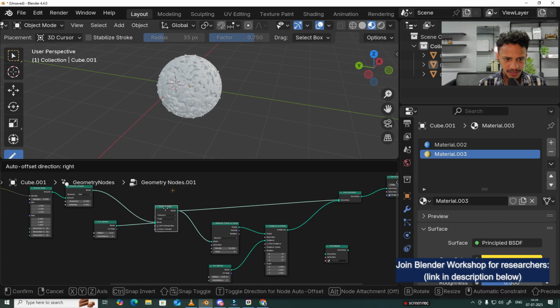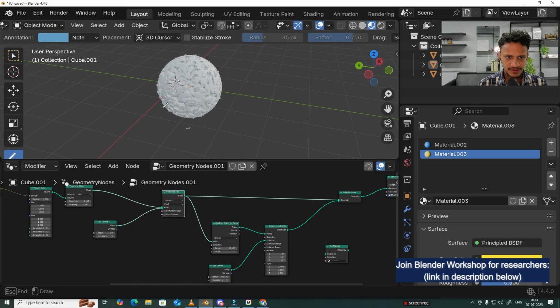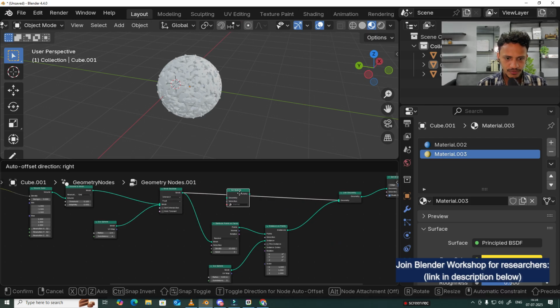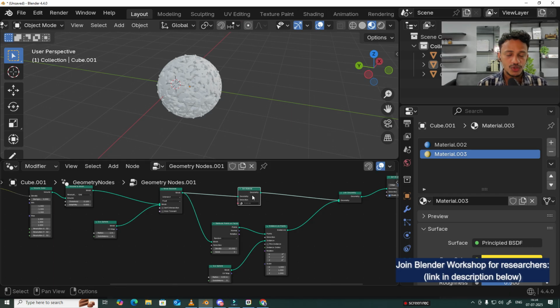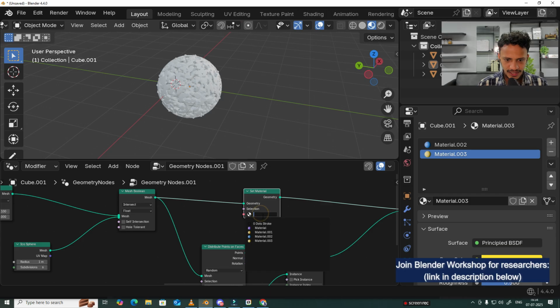First, the mesh boolean output, which gives you the particle itself, and then you have all these tiny spheres. So we need two materials. So add set material first for the output from mesh boolean, which goes to the particle. Once you have added it, click inside the material and choose the material that you have created.